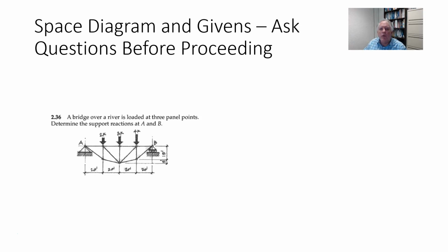Well, what are panel points? Those are the connecting points between the web members and the chord members. And they're the only locations that should be loaded on a truss to prevent problems with bending forces being induced. But this problem is much simpler than it appears. Do we need to know all these things about a truss?